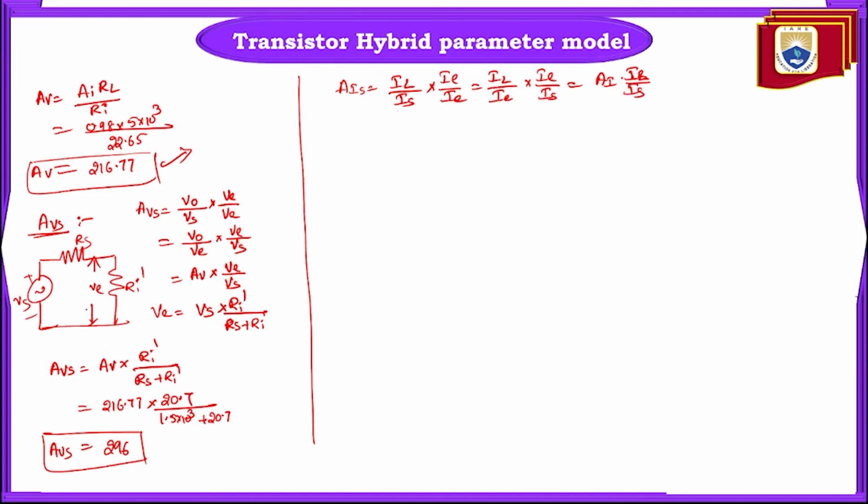For that, I am converting this into the current equivalent, Norton's equivalent circuit. In Norton's equivalent circuit, we'll have a current source in parallel with a resistance, that is Rs, and in parallel with Ri. Re is there before that, and we have Rs as well.